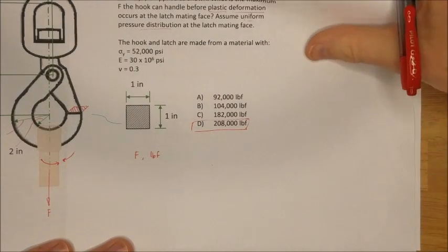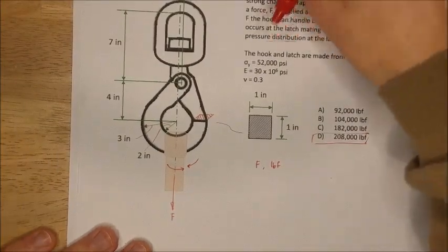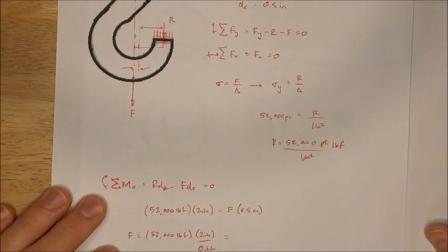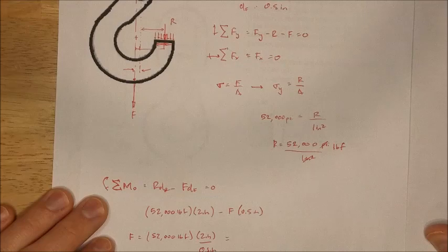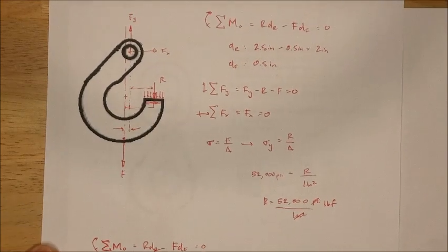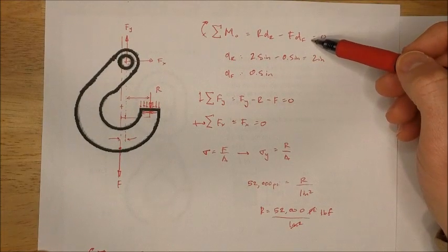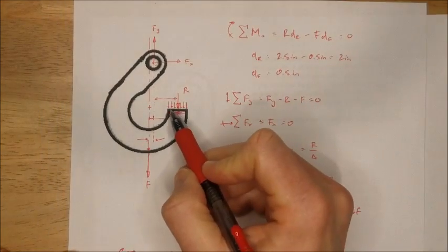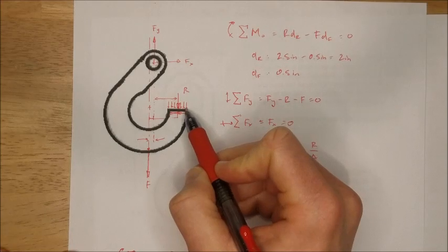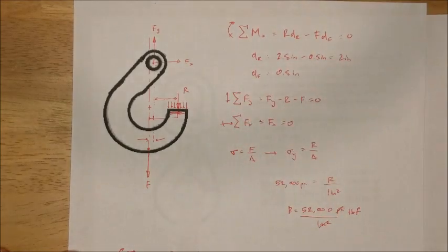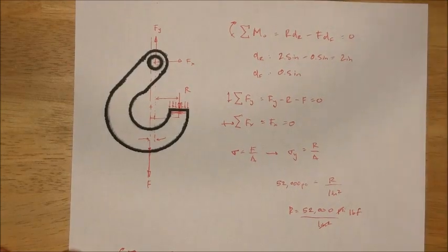All right, that's it. But let's talk about it a little bit. When you look back at the steps we took, it really was fairly simple. And I think that's going to be true for most machine component statics problems. We really only needed one equilibrium equation. But what made it a complicated multi-step problem was a couple things. First off, you needed to know that this was A, a uniformly distributed load, and B, that you could resolve that into one single resultant.